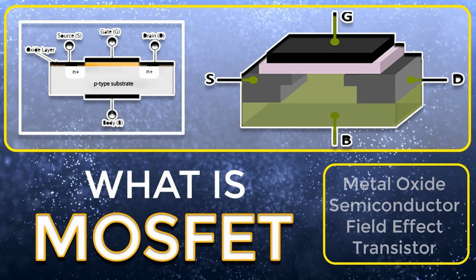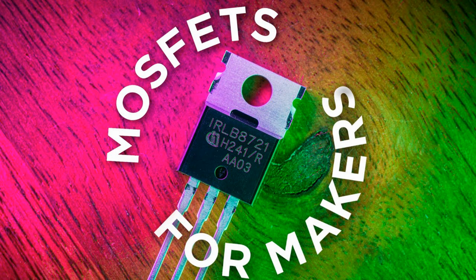Microprocessors. Modern microprocessors are built using CMOS technology. Billions of transistors are integrated to perform complex computations at high speeds. Memory devices, static RAM (SRAM) and dynamic RAM (DRAM), utilize MOSFETs for storing data. Each memory cell in SRAM is typically composed of 6 transistors, while DRAM cells use a single transistor and a